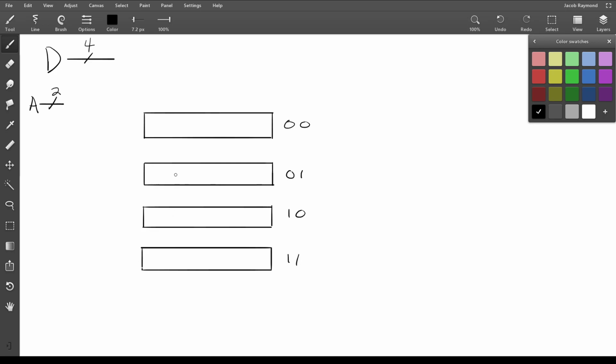So now we need some way of being able to specify which of these we write to. Now, one thing that you really should keep in mind is how the clock works. When the clock is 0, the register will not update the value. It'll just stay whatever it is. So suppose now we just take this data here and we just wire it up to every single one of these registers, just as the D input to the registers. Well, if the clock here for all of these is 0, well, nothing's going to happen. So we can just wire this input to all of them without really needing to worry about anything.